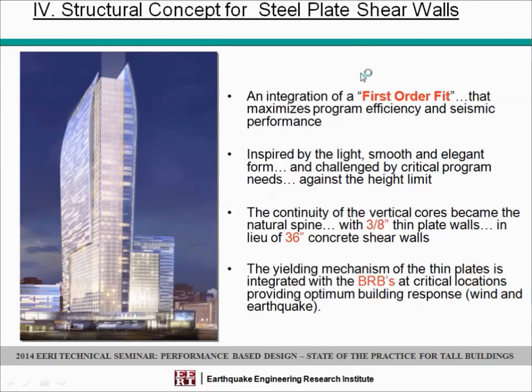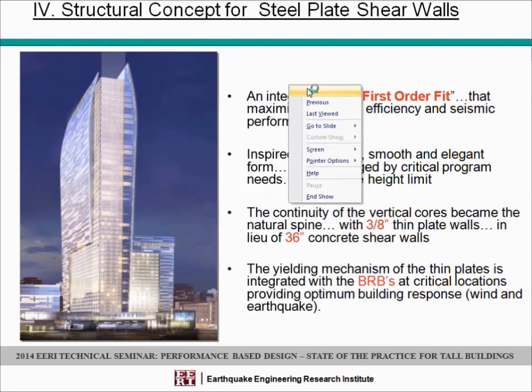Now, here is, in summary, after 6 months of time and preparing both concepts, concrete and steel, it became clear to the developer and contractor that there is a clear benefit in schedule and in real cost, and also efficiency of the floor plate, because of reducing the amount of leasable or rentable or sellable space by having a thin plate system. It's basically an integration of a first order fit between program and structural system. And that's coherent, that maximizes program efficiency.